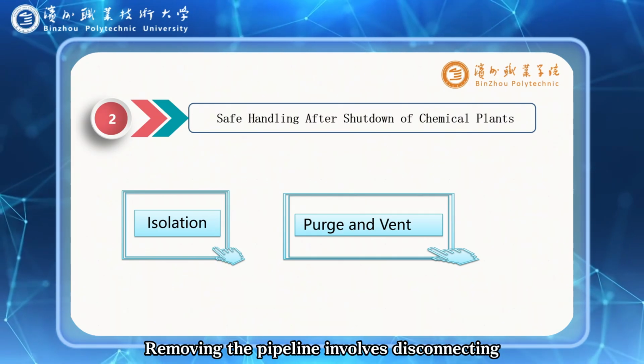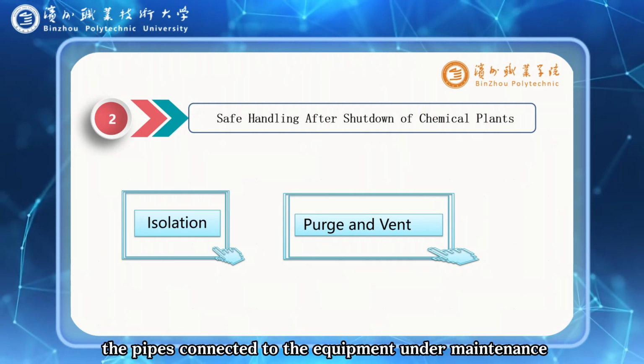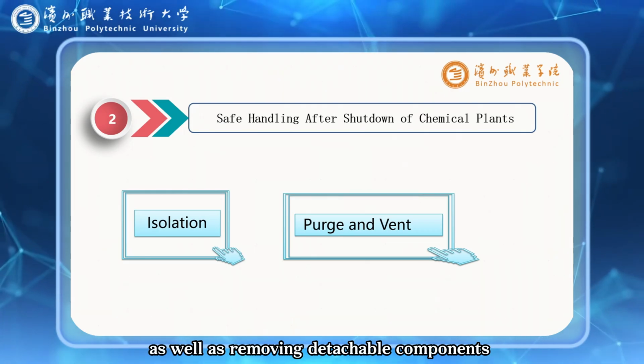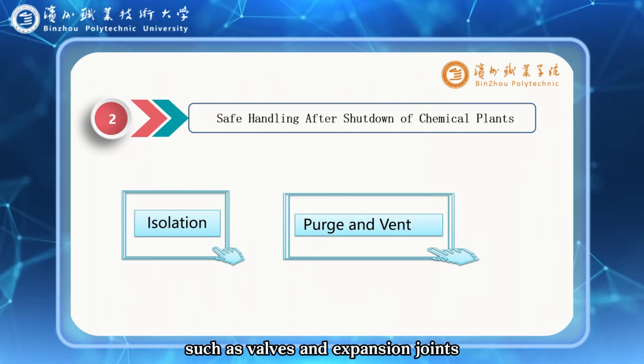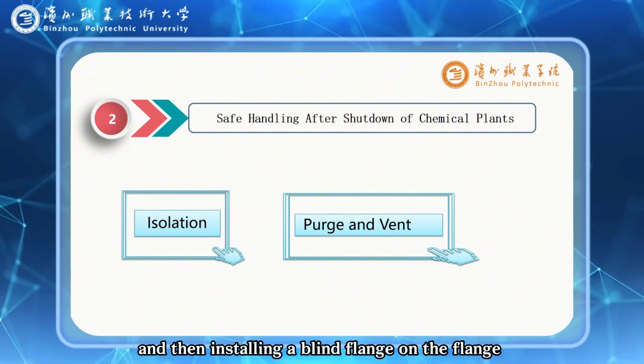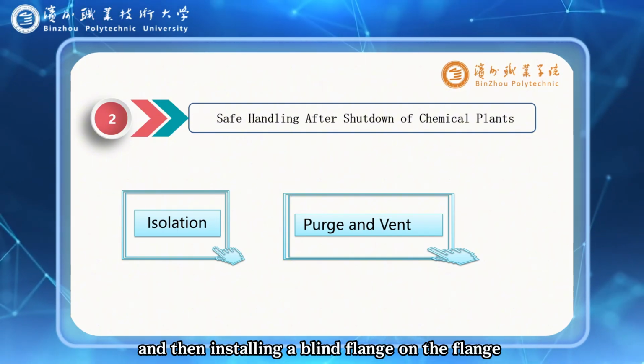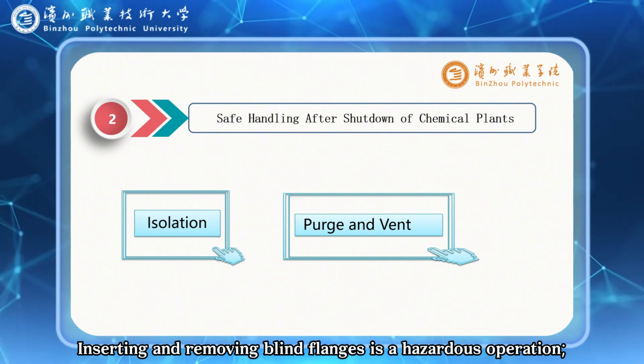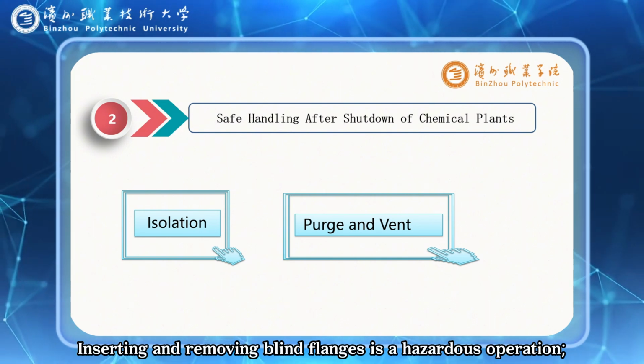Removing the pipeline involves disconnecting the pipes connected to the equipment under maintenance, as well as removing detachable components such as valves and expansion joints, and then installing a blind flange on the flange at the pipeline end.